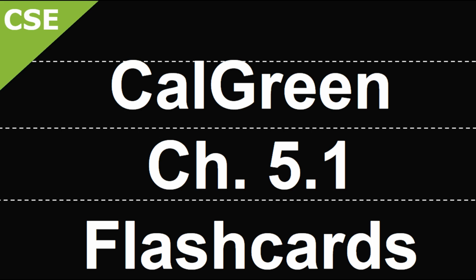So understand the differences again between level 1 EV charging receptacle, low power level 2 EV charging receptacle, and the way to remember those two is a level 1 is at 120 volts, low power level 2 is at a 208 240 volt, but both provide 20 amps minimum. Then we have a high power level 2 EV charger, which is at a 208 240, just like the low power level 2, but instead of a 20 amp minimum, high power level 2 says you must provide a 30 amp minimum EV charger connected to the premises electrical system, capable of charging the electric vehicles.